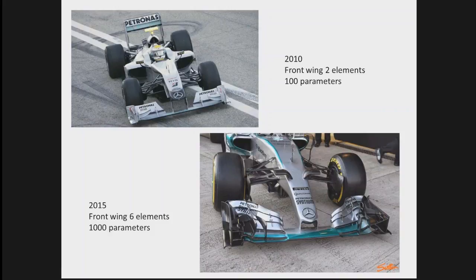So that's when you start to split more. You start to have 3, 4, 5, and now 6. Well, in their case, 5. Some people have up to 6 here. And the same happens in front of the tire. There is a lot of loading going through here, not only vertically, but the wing is sort of going outboard as well. And if you keep only 2 elements, the flow is not going to stay attached. So you add more elements to keep the flow attached, because some more air is coming along the wing, if that makes sense. Okay, Milad?